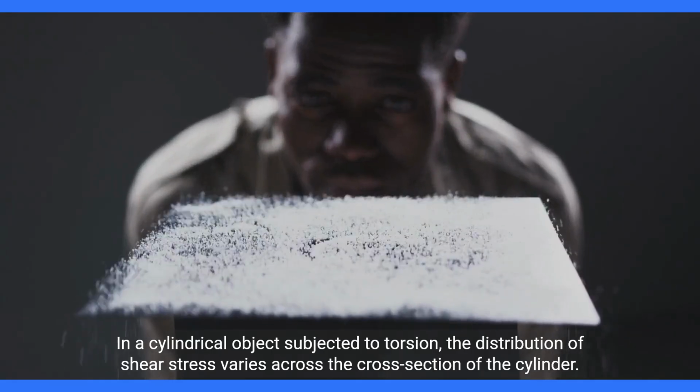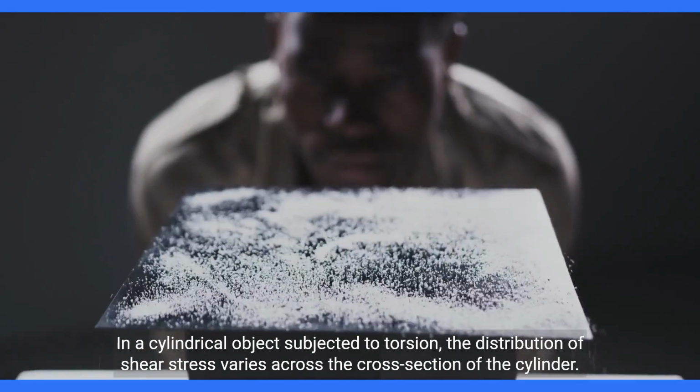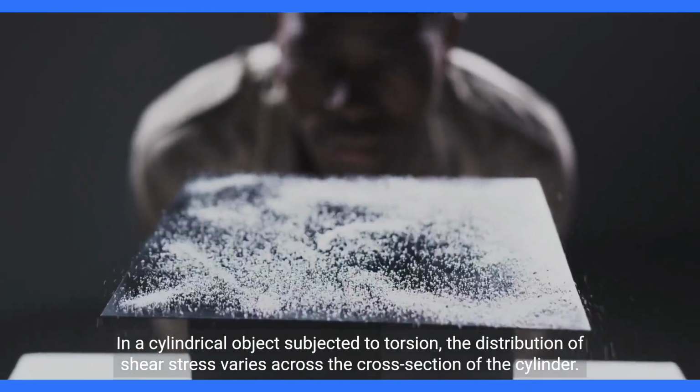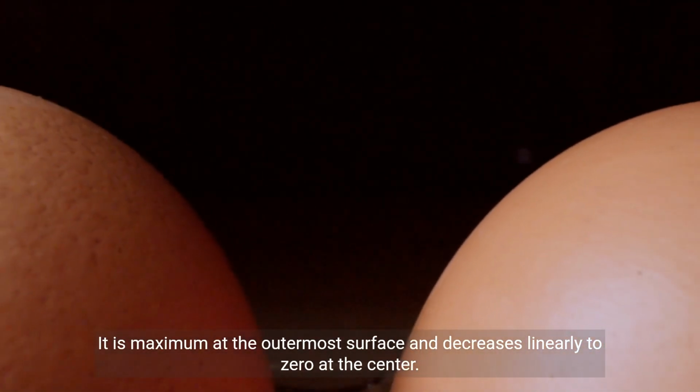In a cylindrical object subjected to torsion, the distribution of shear stress varies across the cross-section of the cylinder. It is maximum at the outermost surface and decreases linearly to zero at the center.